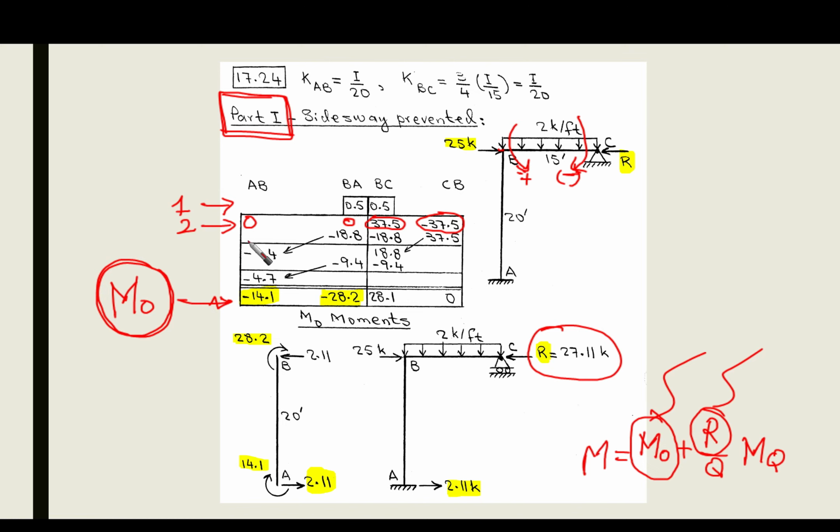So now, after obtaining the distribution factor and the fixed end moments, we are going to use the usual way for moment distribution. We are going to use our moment distribution procedure, which we already explained in the previous 2 videos. Simply as a reminder, at point B we have a 37.5 unbalanced moment. We are going to distribute it with different sign, take care. Half and half, because we have distribution factors 0.5 and 0.5. This means that we have 18.8 here and 18.8 here with negative signs.